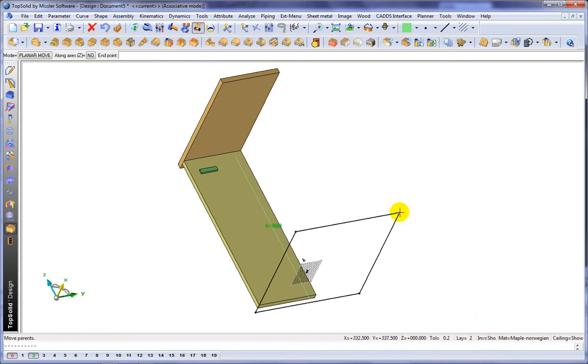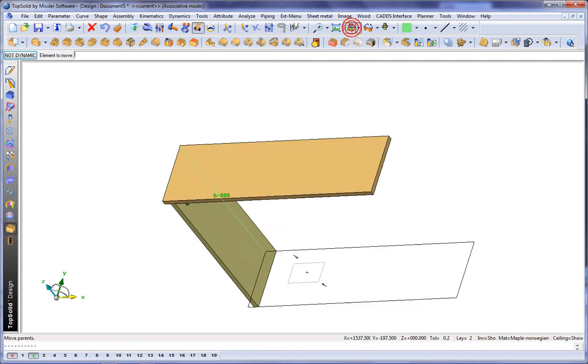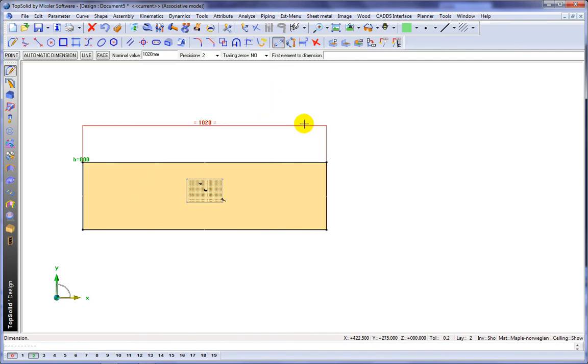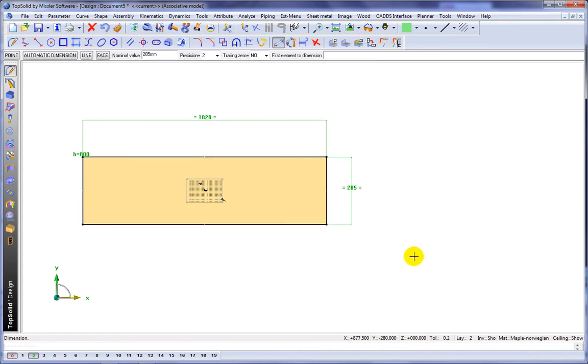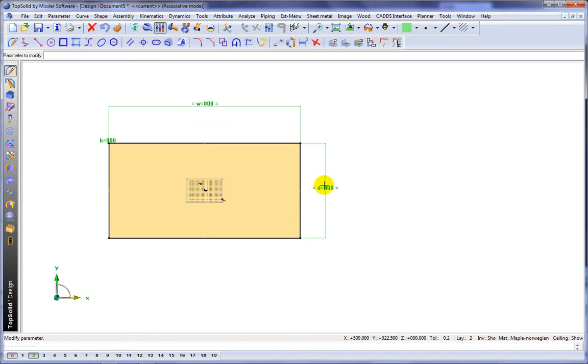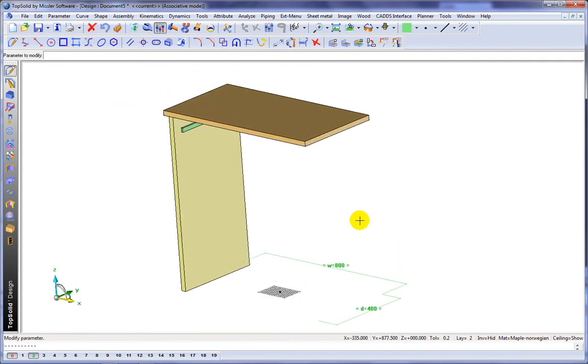Now if we drag this sketch around that created that initial volume, you can see that our parametric design is doing exactly what we had intended. So now we're going to make it a little bit more parametric, and we're going to add some driving dimensions to that initial sketch. And we'll make them symmetric about our 0. Add this one, make it symmetric about our 0 as well. And then we'll modify them, set them to some kind of fixed value, as well as name them. So you can see, nothing very difficult here. And like that, those dimensions will be used later to drive the overall width and depth of our design.